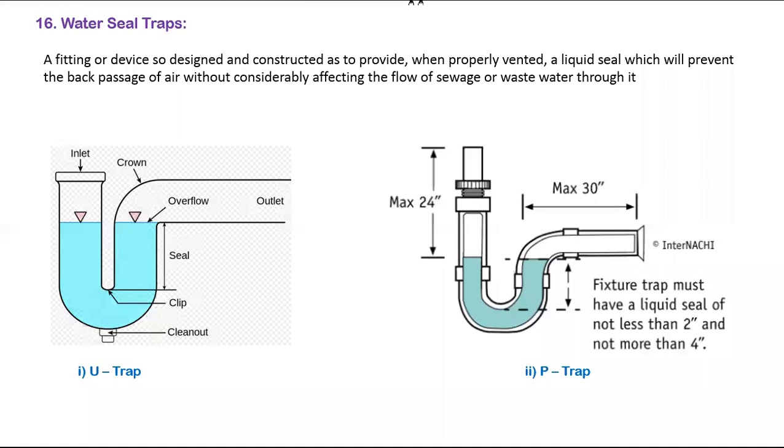If you are not using the bathroom because you are going on some trip or vacation, after coming back to your house you see there is no water in your IWC or EWC. Your total house will smell because of foul gas. Why? There is no water in the U drop or P drop. Everything dried, then only you will get the smell.